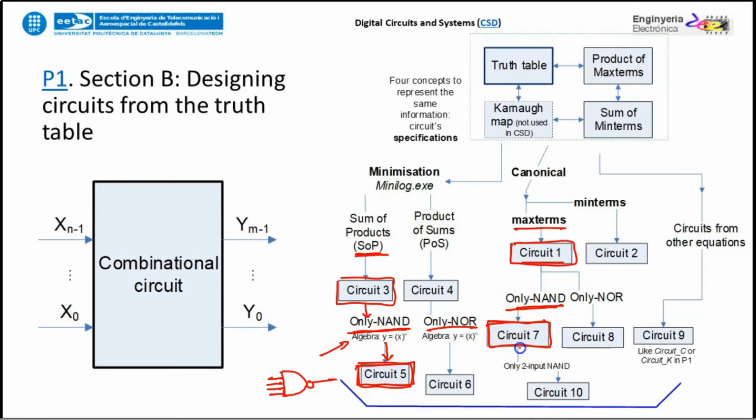But now there is even another constraint that you can impose here. For example, you may say: let's have a circuit which consists of only NAND, but let them be 2-input, all of them. So the NANDs in the end happen to be all of the same kind, like this, 2-input NAND, okay? This means that, for example, in the past, all the digital circuits could be designed using the same chip, for example the 74LS00. That was the case in the past.